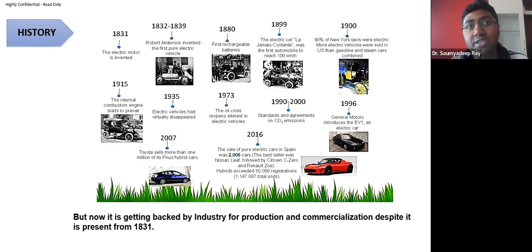But if you charge it at 80 ampere, then it will take half the time, so 4 hours. If you increase it up to 4C, the battery is the same battery, and it will take 2 hours. So the time reduces with the battery technology, and charging will be much faster.